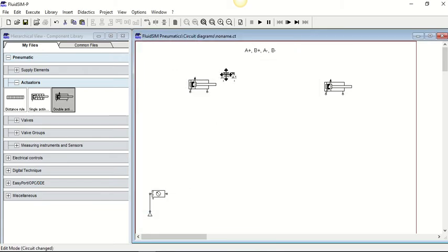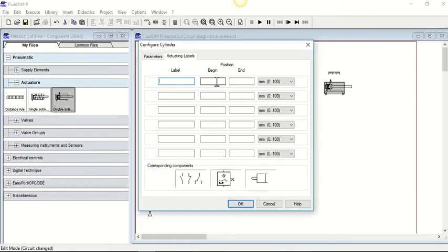And what I like to do is pull that roller over. You'll see if you pull it over, it just sits on the outside, so you can see the roller switch hitting off it. It makes it a little bit more realistic. I suppose if you had it on this side, you'd nearly be using magnetic proximity switches sitting on the cylinder housing itself. And we're going to have the same on the B side, so B0 and B1, and we'll go 0, 0 and 100, 100.